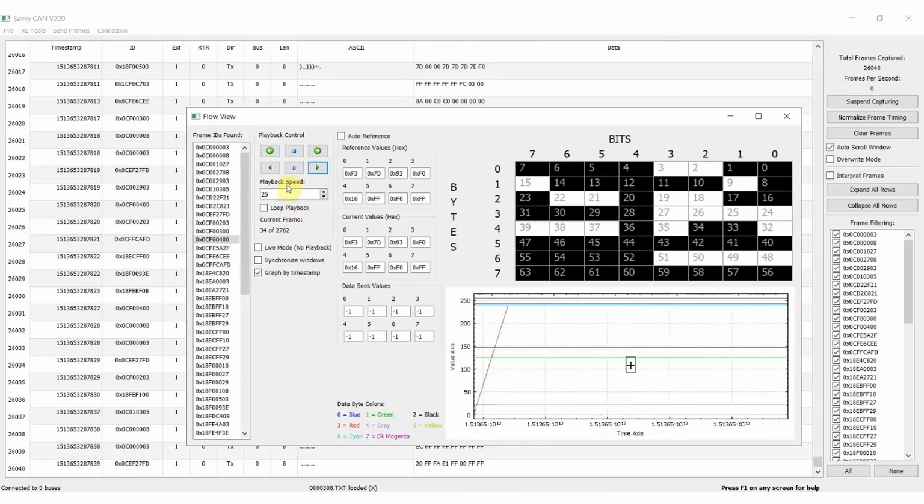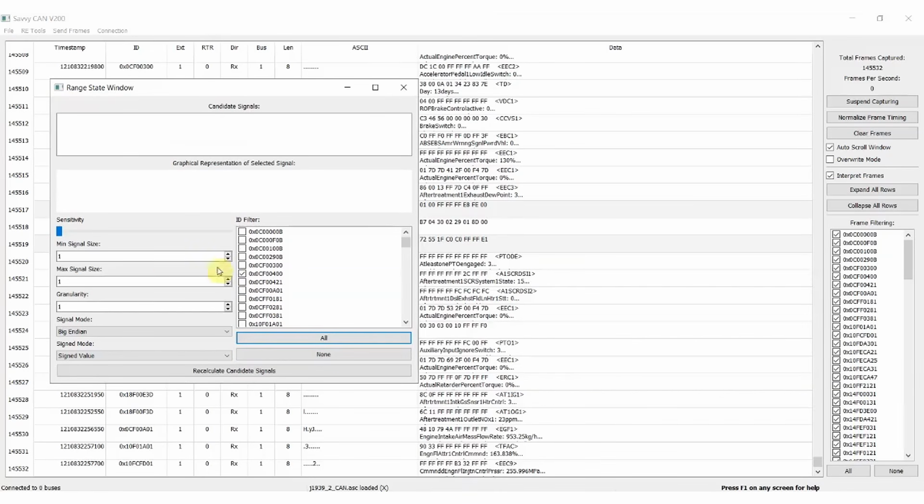The problem with doing reverse engineering in practice the classical way is that you essentially need to be a bit like Tank from the Matrix. You need to use tools like SavvyCAN, and you need to do a lot of ad hoc human analysis on the fly, where you're looking at bits of the CAN data bytes that are flipping. You try to correlate this versus what you're seeing in the real world, and if you get really good at it, then you are able to, in many cases, reverse engineer at least some CAN signals, but it can take hours to do so. And in my opinion, it is only really possible if you have some serious expertise within the field.